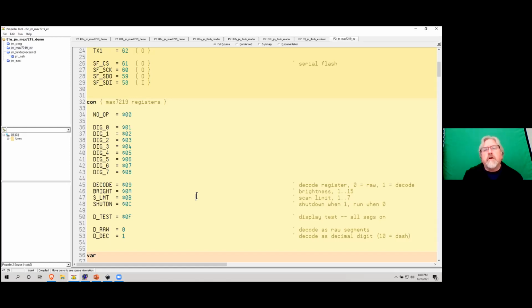So you'll notice in the code, as you get down to the bottom, I have built-in character maps for all the digits, the uppercase that look proper, the lowercase that you can pull off, like a lowercase c or lowercase o or lowercase n. You can't do all letters. That is the disadvantage with 7-segment displays. But the ones you can, I have maps for, and I have methods to make it really easy to write any letter or any digit that it can display to any position. So I bypass the internal logic of the decoding and just use it as a raw device. I find it makes it simpler.